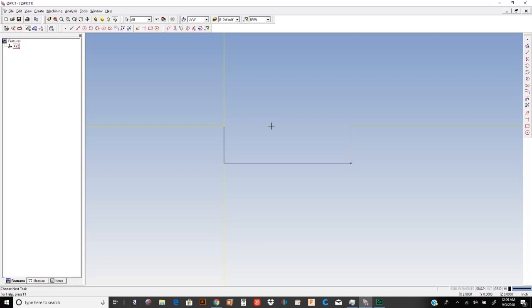The way it works is if I go to select this vertical line right here, it gives me an S4 and a question mark on the mouse. Okay, so S stands for segment. So it's saying segment 4. Do I want to select that? And yes, I want to select it.